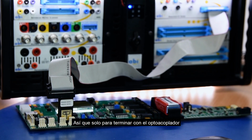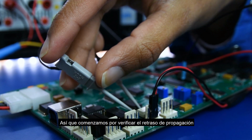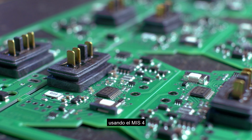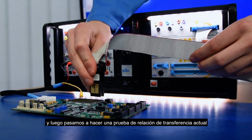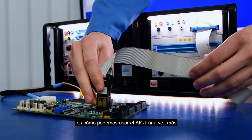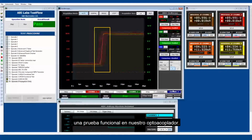So just to finish off with the optocoupler, Oliver has shown us how we can use the BoardMaster to do several different tests. We began by checking for the propagation delay using the MIS4, and then we moved on to do a current transfer ratio test. Now what Oliver is going to show us is how we can use the AICT, yet again, which you can see in the previous episode, to carry out a functional test on our optocoupler.